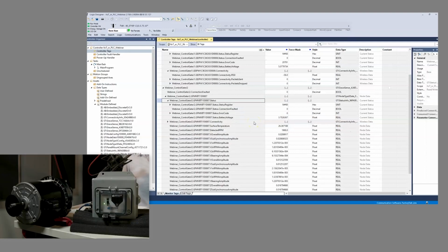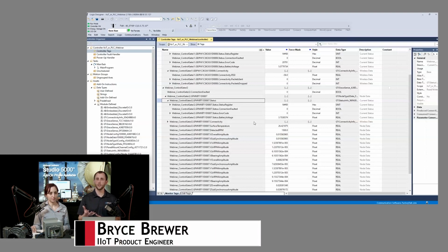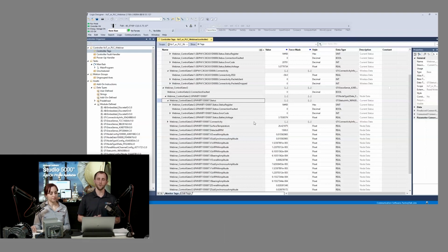The gateway basically got the new configuration from the PLC and rebooted and applied that so it could readopt this now that we switched control as the source here, which I suggest for most of our industrial customers who are integrating this to have the control as your source of truth and what's telling the gateway how to react, so that if I do make a change here, it does impact the gateway. If you didn't do it that way and you made a change here and it was set to CloudGate, being the maintenance hub would be the master, then it would not be reflected. So it's just kind of a trade-off on which one do you want. Do you want to go into the maintenance hub and make all your changes there, or do you want to do it through your Studio 5000 environment?